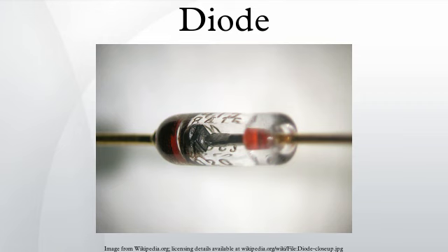The value is different for other diode types, as Schottky diodes can be rated as low as 0.2 V, germanium diodes 0.25 to 0.3 V, and red or blue light emitting diodes can have values of 1.4 V and 4.0 V respectively. At higher currents, the forward voltage drop of the diode increases. A drop of 1 V to 1.5 V is typical at full rated current for power diodes.